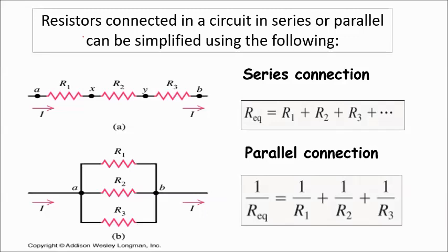No? So a combination of resistance in an electric circuit can be used to provide a right amount of resistance in the circuit. So if a single resistor of that amount is not available, we can use a varying combination, series or parallel, or a combination of series and parallel to get the required value of resistance.